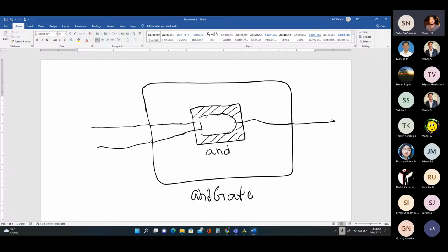On top of the black box, my inputs are A, B, and output C, and inside this, the placement we call technically as instantiation. So what I'm doing is taking an instance of an AND gate structure from the library and placing it within my module, and making the interconnections. This is called structural level of abstraction.